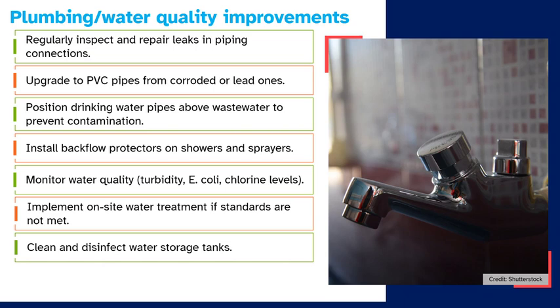For rainwater collection, cleaning gutters and roofs monthly and utilizing first flush devices and filters can help remove contaminants. If water quality is compromised, for example by flooding or other source of contamination, flushing the system and implementing appropriate water treatment methods can restore water quality.